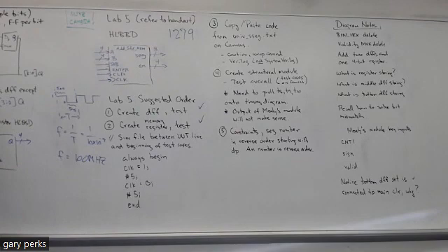And recall that in SystemVerilog and also Verilog, if you have double slashes, what follows is a comment. So what can happen is the comment gets split up, half of it gets put on the line underneath, and it doesn't have the double slash. So then it's being interpreted as code, which doesn't make any sense because it's a comment. And that causes all kinds of errors. So just be careful about that.